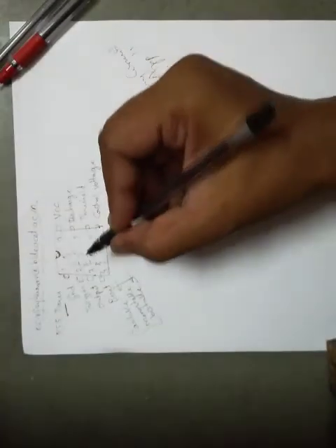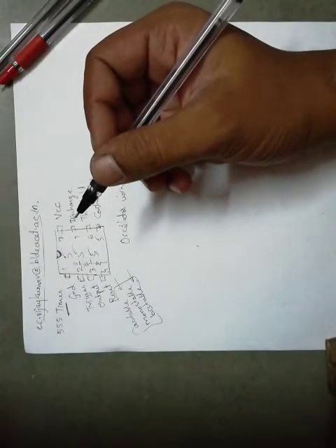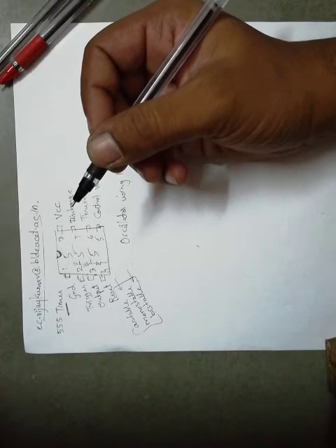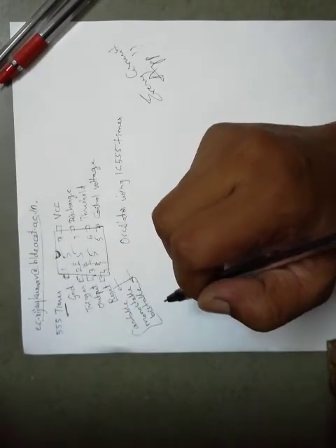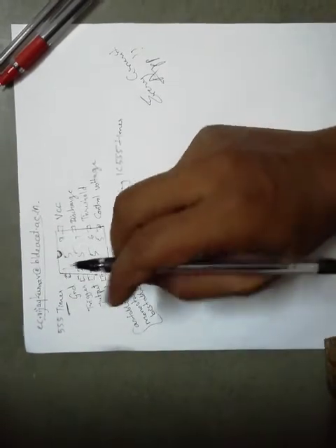1 and 8 pins are ground and VCC. 4 is reset, like reset in any other IC. It will reset the working of the design, means back to 0. Then we have 3, the output, where we are collecting the output of the timer. 2 is the trigger signal. As the name indicates, it triggers the output to go low.